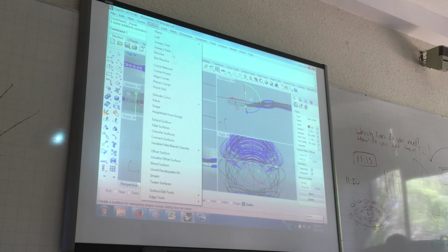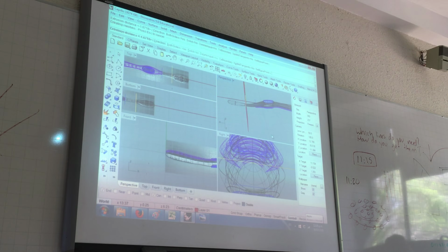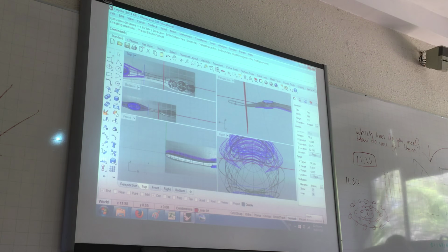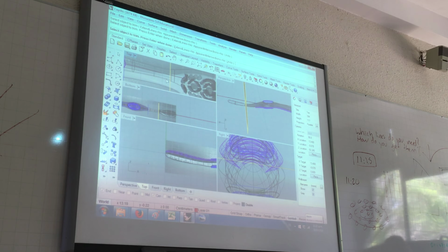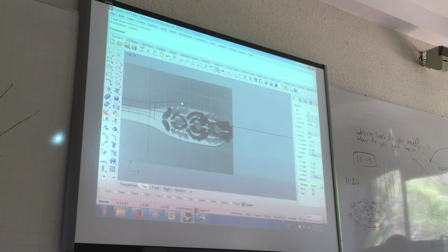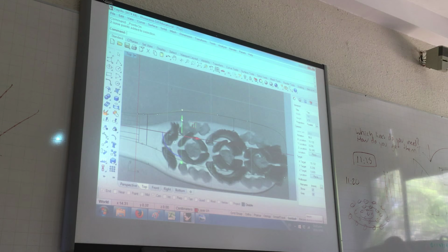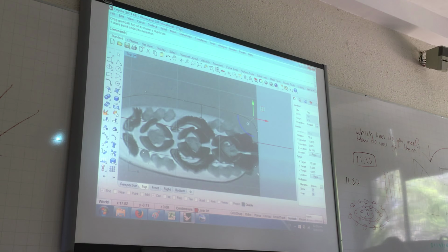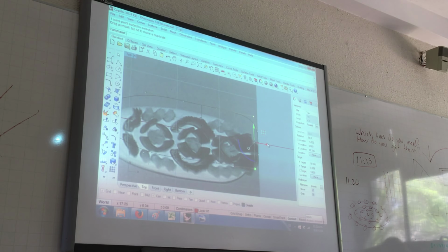I'm going to extrude this straight both sides so that it intersects, and then I'm going to trim it. This is the cutting object, and I want to cut this and this. No, I still have my original curve. And so what I can do is adjust this a little bit because I don't really like how it looks. I can move this and make it squarish, which is what I'm trying to achieve. I think that this should go higher, something like this, and maybe even further in this direction to make it look squarish.